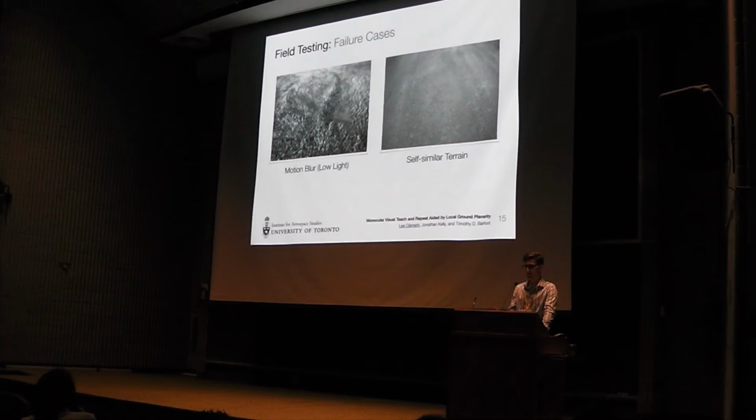SURF matching is sort of independent of what you're actually doing with it afterwards. But what made it difficult for monocular is that we had all this extra spatial uncertainty in our pipeline, that you can think of as expanding the bubble in which we have to search for candidate feature matches. And so if we're coming up with a lot of ambiguous feature matches, then we're going to have a hard time choosing which is the best one, and our localization is not going to work out so well. So that was the problem.